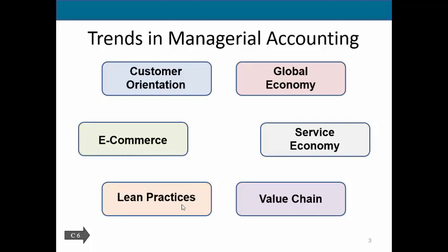Let's say it's now been put together and now we need to paint it. That movement, when it moves from point A to point B, we are not actually adding value in that area. Instead, we're wasting time and resources because it takes either labor or some type of machinery to move our goods. So with lean manufacturing, we want to get rid of any of those activities that do not add value. And that might be through rearranging your manufacturing facility so that you don't have to actually pick up things and physically move them. Instead, you'll lay things out so that they run more smoothly.